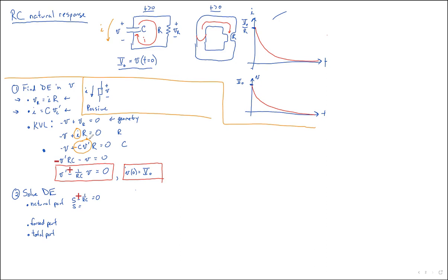That's a really subtle thing that probably was not a big deal in circuits 1, but will become a big deal in circuits 2. That the constitutive relationships assume a passive sign convention. So if you're not going to use a passive sign convention, you've got to put a negative in front of one of these things. Questions on that?